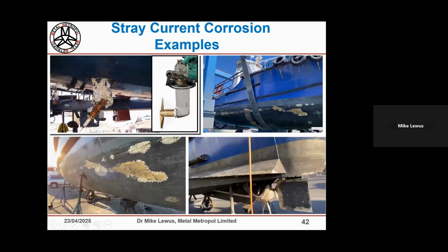You'd get poor isolation, you'd have the risk of galvanic activity, but you'd also have monolithic, if you like, engineering structures that were very prone to stray current corrosion.